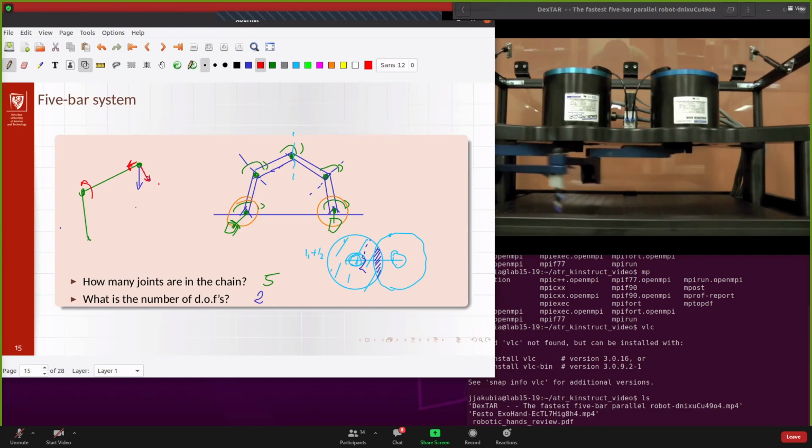So part of the force influences this motor. But if we apply a mass, keep an object that is under gravity, and let's say we keep the manipulator in the position and the mass is still here, this part of the force is the bending force that tries to bend our arm.